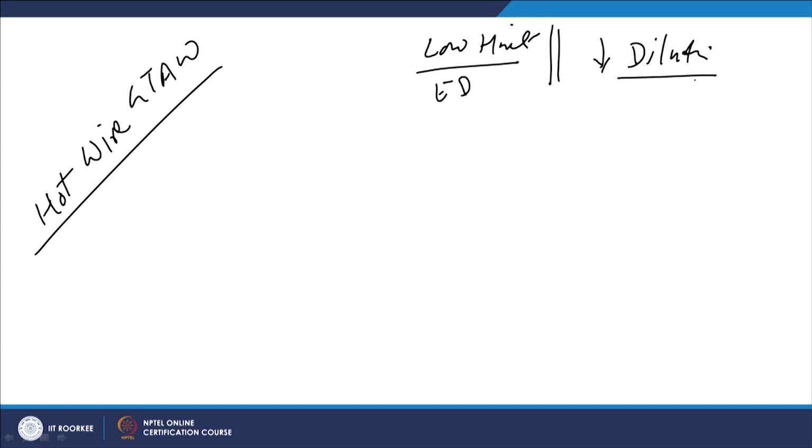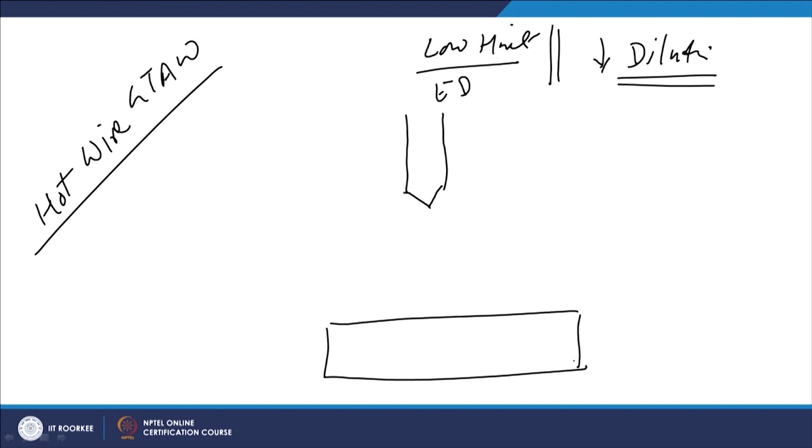That is, the quality of the material which is being deposited is degraded to lesser extent due to the limited melting of the substrate and getting it mixed with the filler metal which is being deposited. So, the reduced dilution associated to the GTAW process is another positive side, but we need to overcome the low melting due to the low deposition rate issue related with the GTAW process.